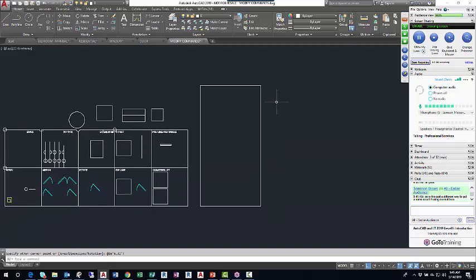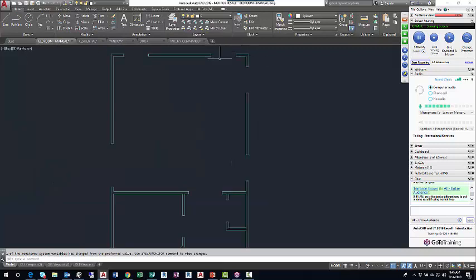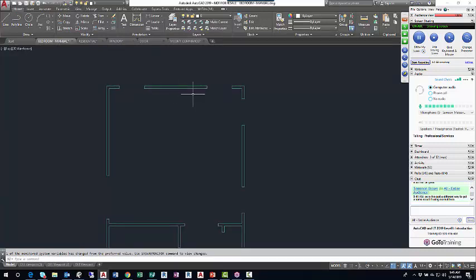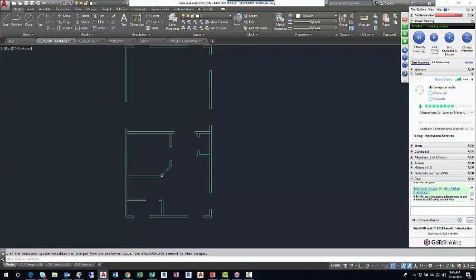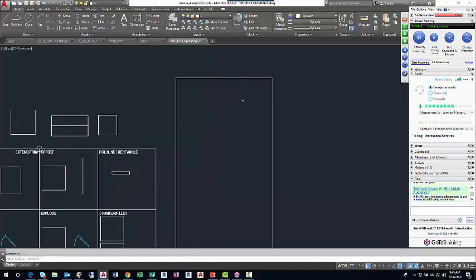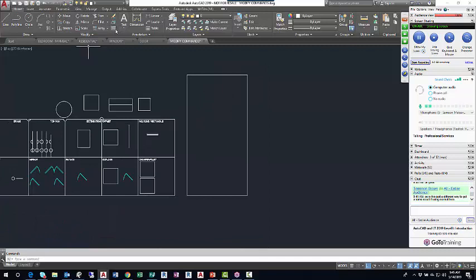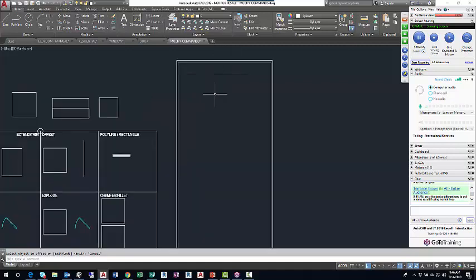But one of the upcoming commands is a command called offset. We're going to use offset to create the illusion of a 2 by 4 wall, or a 3.5 inch thick wall, and so forth. So what happens when I use offset on a polyline? I'll go offset, 3.5, enter, left click the polyline, move inside, and left click. It offset all 4 sides because that was a polyline. So yes, it's a different way to draw the same thing I could draw with lines, but if that were 4 lines, I'd have to do 4 offsets. And then I wouldn't have the neat corners that I have here.